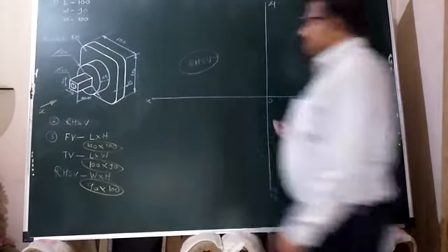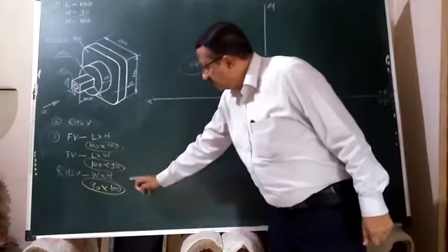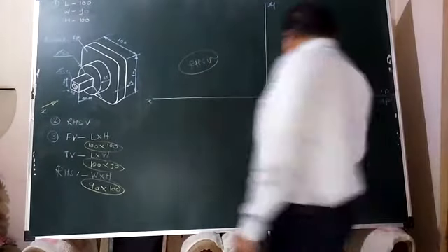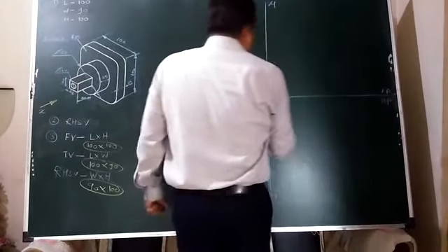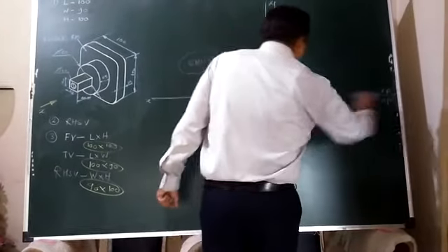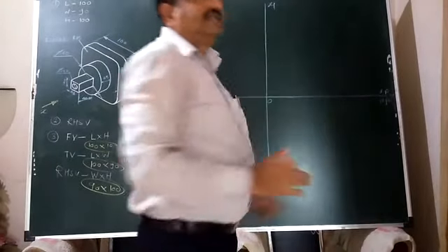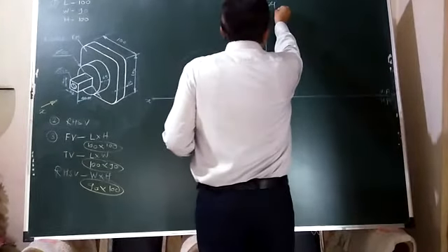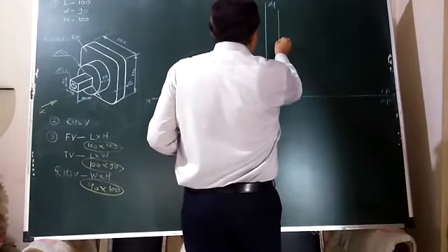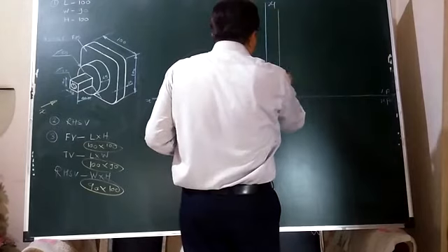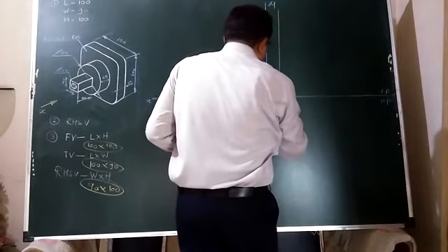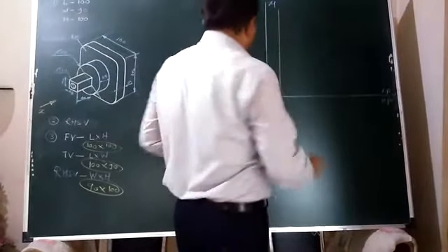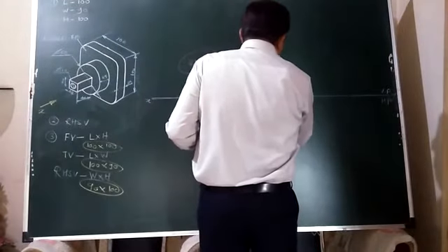Now the areas or these plots, 100 by 100, 100 by 90 and 90 by 100, we should fit here. For that, the very next step is: parallel to HRL and parallel to VRL, at a distance of 20 to 25 mm, we should construct 2 construction lines in this way, only over VP and HP. No need to construct this line over the profile plane, because automatically the same distance will be carried forward by using a compass.